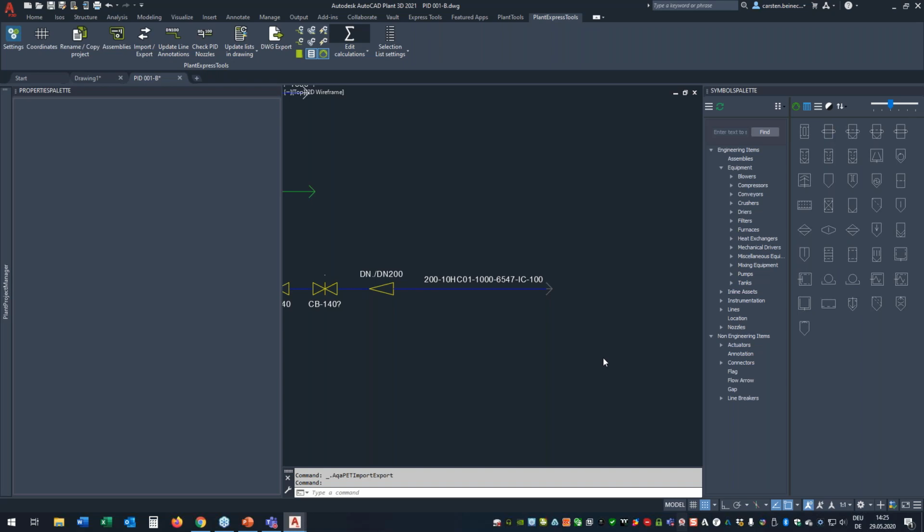And it's not just about service, of course. That's just the example I have here. It can be any sort of list. Maybe you have a list of pipe specs for PNID you want to see, and maybe there's some change in the project. So you maintain the pipe spec names in Excel, and you want to, of course, then eventually refresh the selection list in your project based on that external Excel sheet or database table.